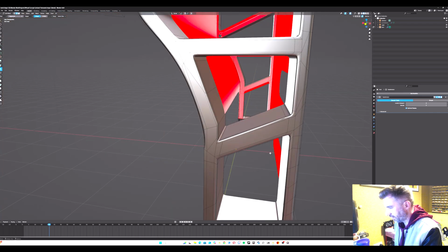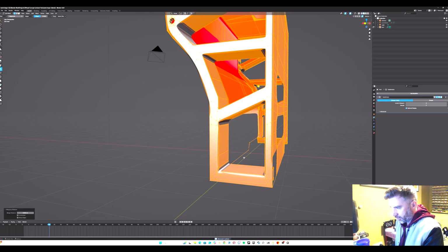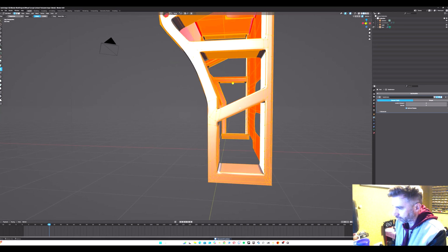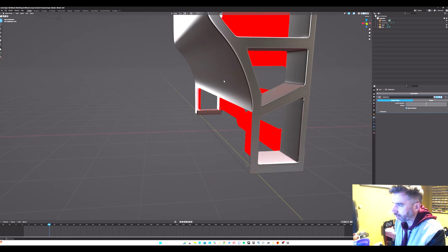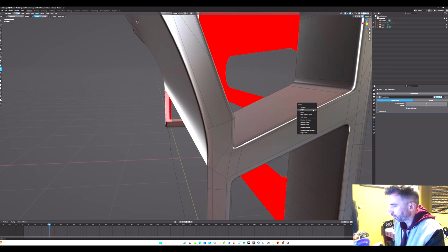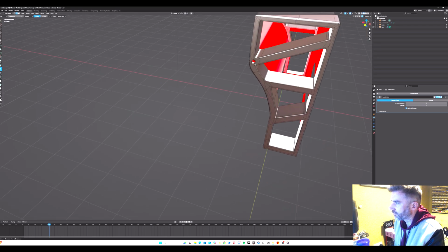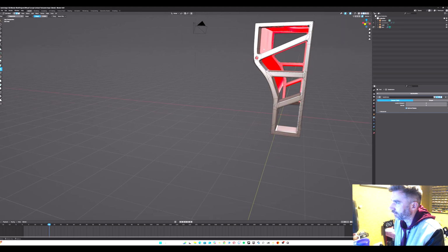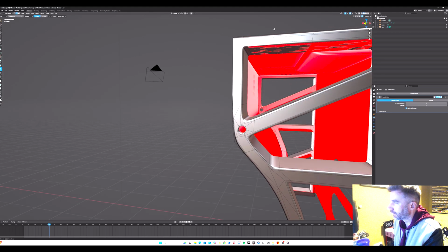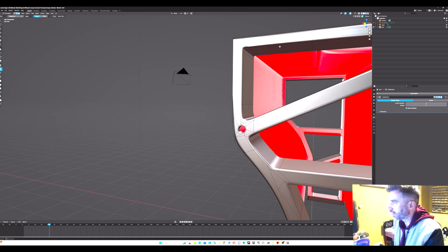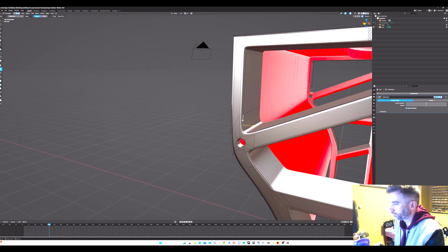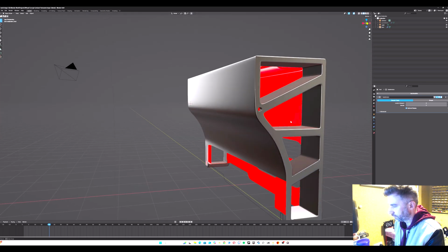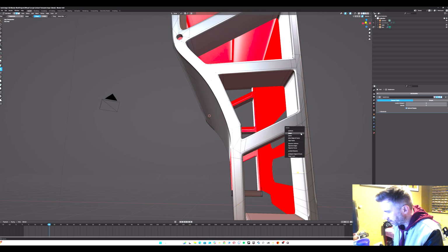Yeah, we've got some extended edges. I'm hoping if I do merge by distance, I'm able to fix some of those issues. Apparently not. So this is what happens when you get a bit lazy and you just duplicate geometry over. So I'm just looking for anywhere where it's, so we definitely got one there. And we've still got some weirdness going on up here. Delete that edge, yeah, I fixed that. That edge. Something's still not right here because we've got that edge.